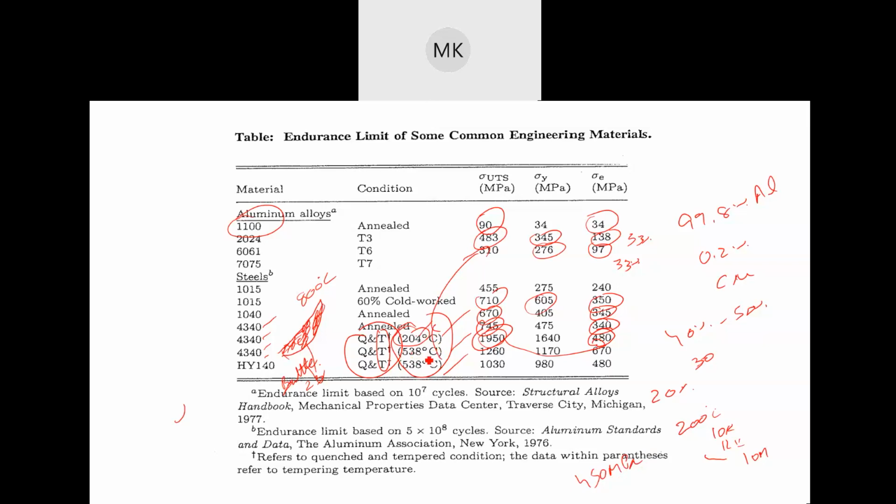So let's say I do the same thing at a higher temperature, very close to one third of its melting point, or higher than one third and a little lower than one half of its melting point. When I do that, I lose some strength in the material, but that's fine because I'm getting a higher endurance limit. So I can use this material for my landing gears because of the high stress I'm going to have for impact landing.